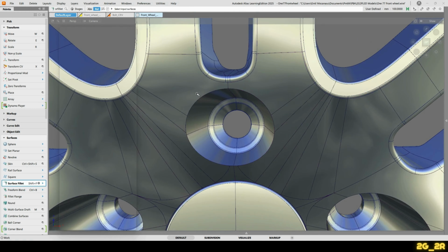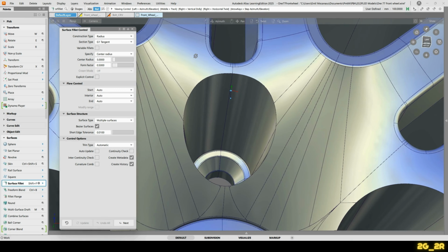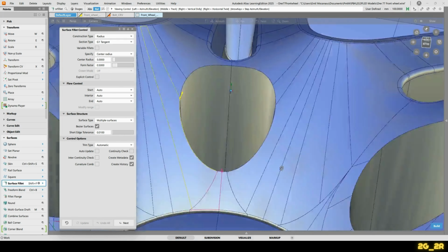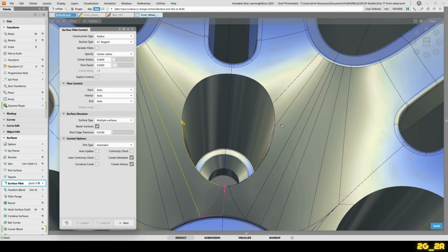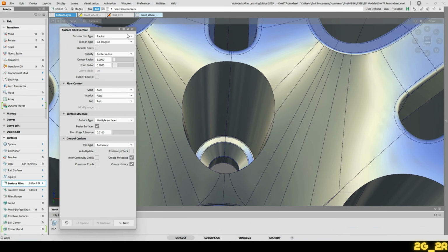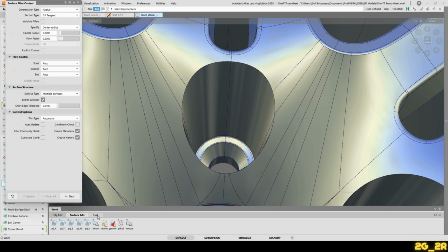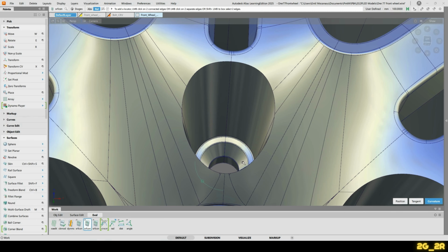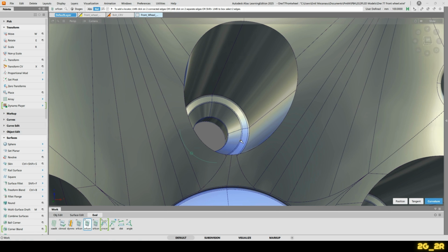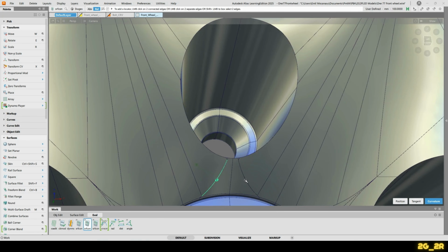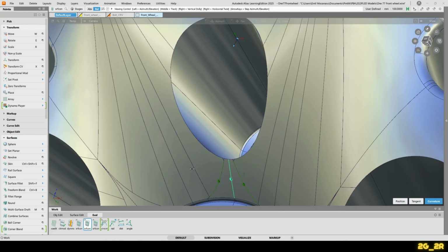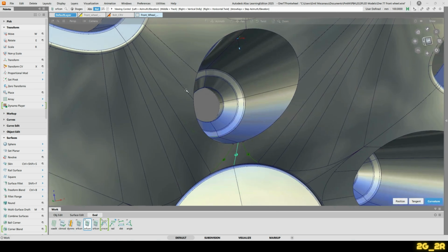So what you see here is first mistake picked up by the tool itself. If I'm clicking between these two, normally you should be able to go all the way around, and it doesn't in the same color because we've got tangent break between this surface and this base surface there. So we can evaluate that. Wrong selection. And it doesn't do it. Funny.